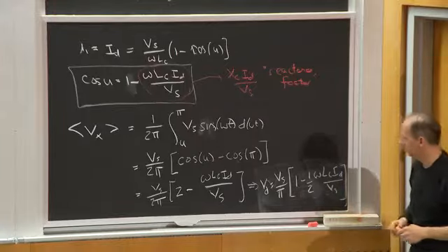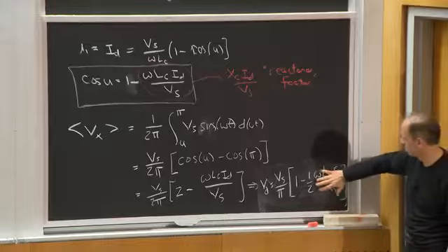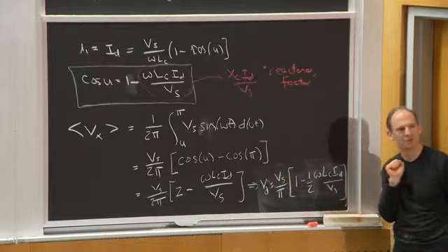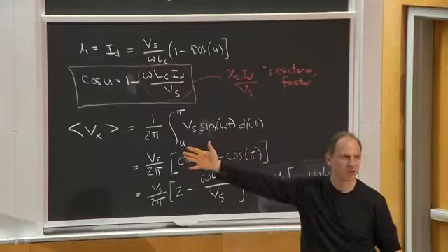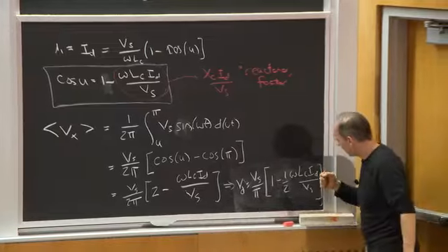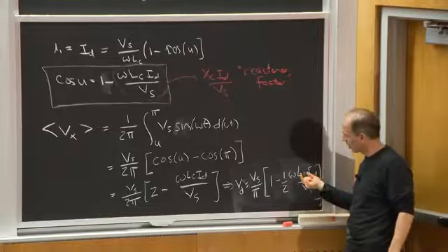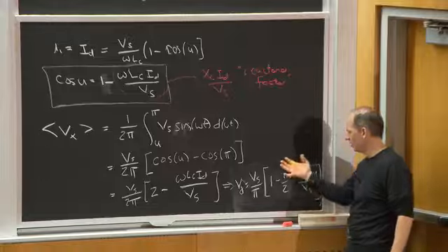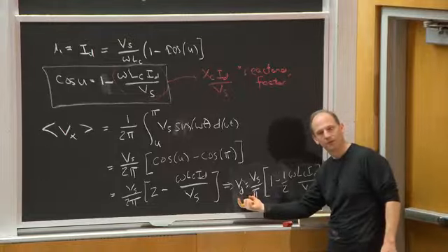What it says is this. Suppose LC was 0. This term would be 0, and I just get Vd as equal to Vs over pi, right? So that makes sense because my first analysis was with LC equals 0, okay? But as any of the load current or the commutating inductance or the frequency increase, this tends to degrade my output voltage, okay?